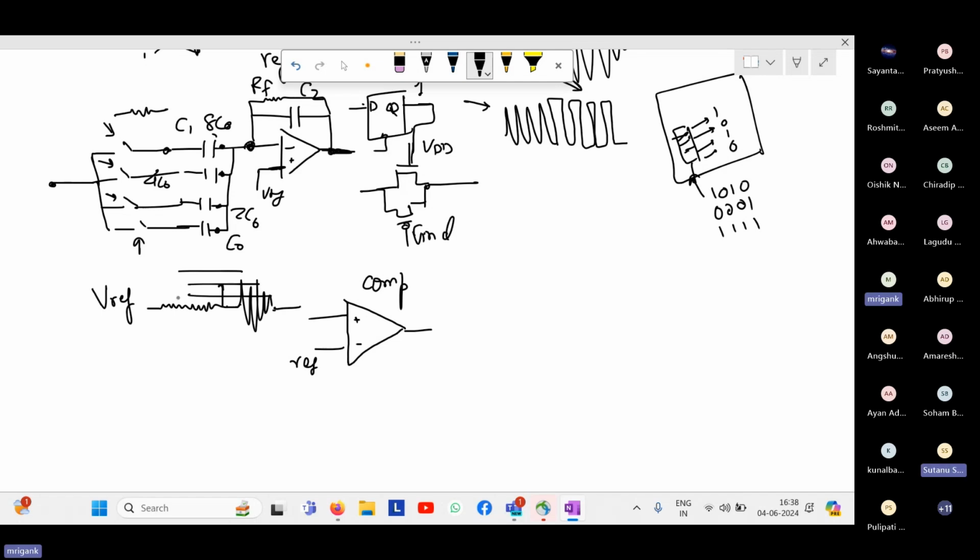This delta that I'm talking about, ultimately it will be VREF plus delta. I should call it VREF A, VREF of the amplifier. So this VREF A is the reference of the amplifier, and the DC level of the output of this amplifier will be VREF A. So this reference will be VREF A plus delta. This delta will decide the threshold, right? So whether this should be the delta, this, or this.